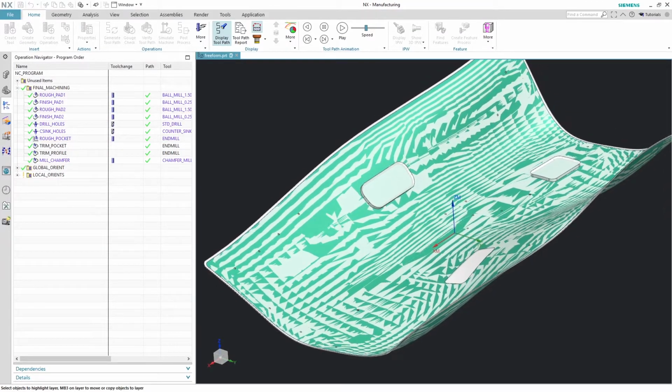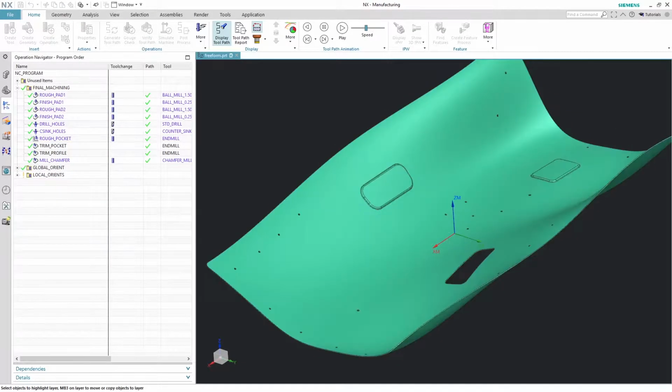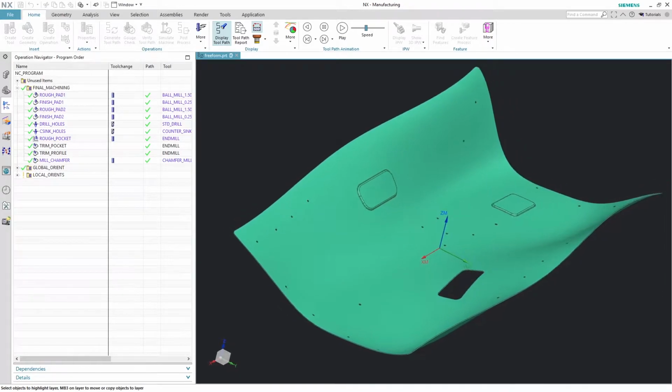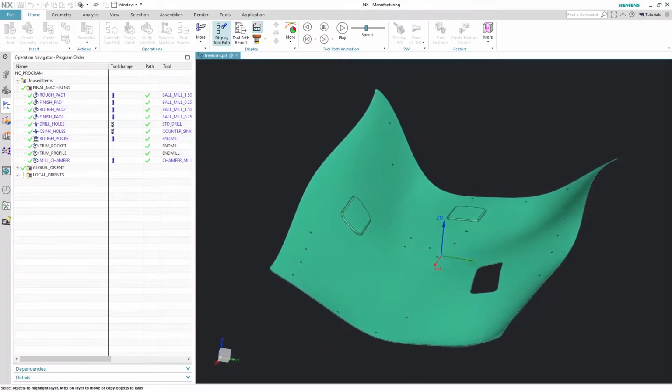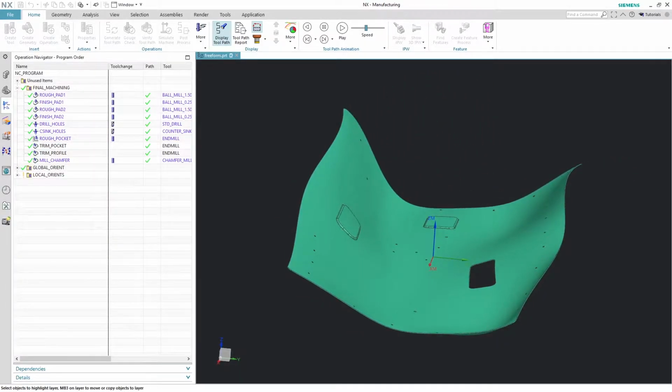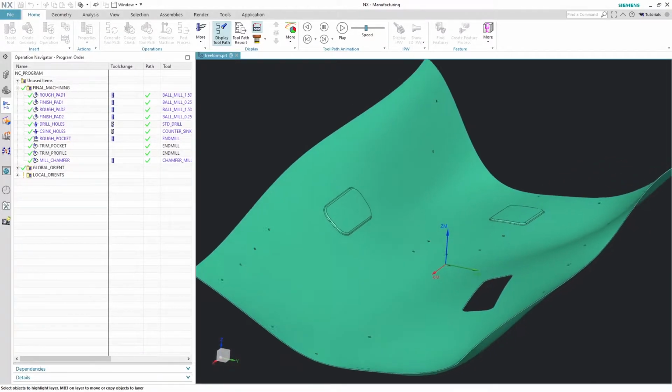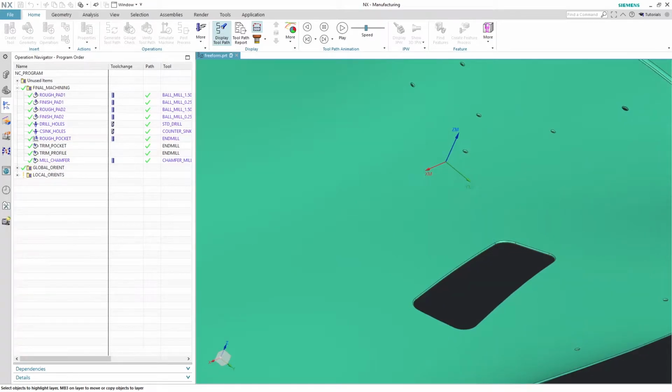As you can imagine, a part like this would be very challenging to manufacture for a number of reasons. First of all, the setup on the machine would normally require a very expensive precision fixture and a highly skilled operator. To make matters worse, the actual part surface would likely vary significantly from part to part, making it very difficult to hold tight tolerances on the pad thickness, countersink depth, and chamfer size.